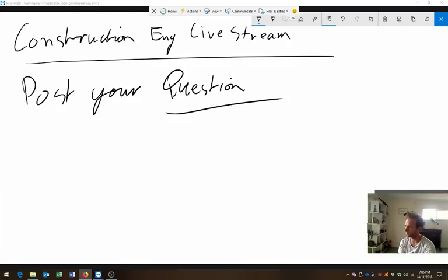I'm just checking the last part of this question. Yeah, so I mean, both dewatering systems, if you're in sand with a high water table, are not going to be economic. It doesn't sort of matter if we do deep well dewatering or PVC spear dewatering. It's simply not going to be an economic solution unless we create a water tight barrier around the basement.